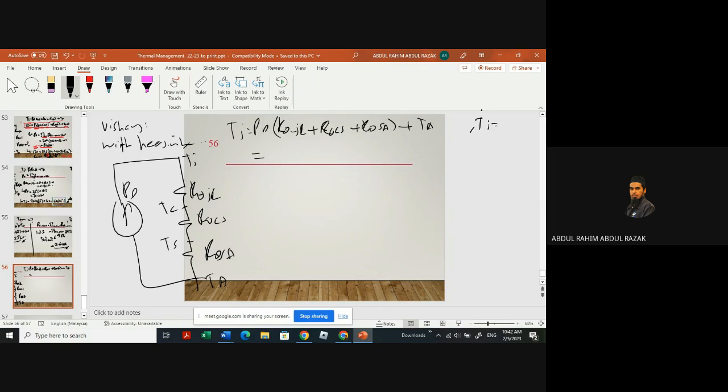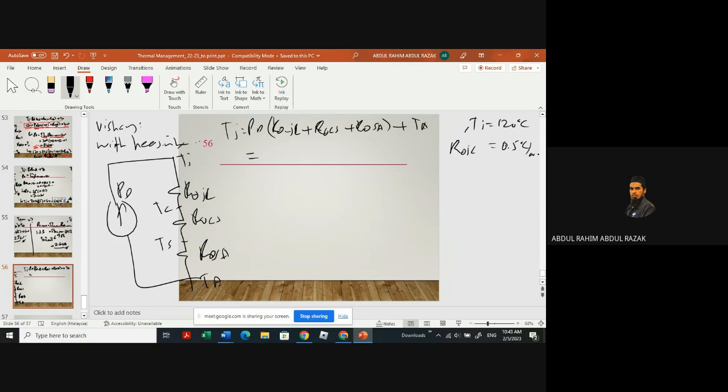So your TJ is 120 degrees C. Usually, thermal JC will be provided. This is the thermal paste, which will be provided. This is the part that you have to find out: heatsink. Okay, junction we set at 110 degrees C. PD is the amount that we have to calculate when we conduct IRMS maximum, which is 20 amperes now. Thermal JC comes from the datasheet. This is the unknown that you have to calculate; this one is already provided. The ambient is 40 degrees C.